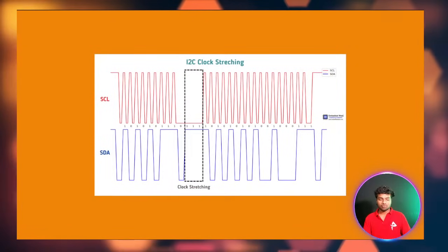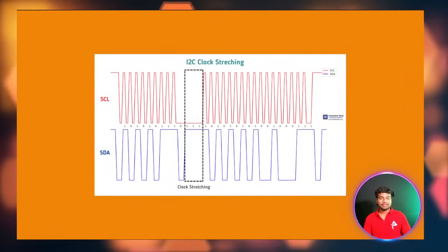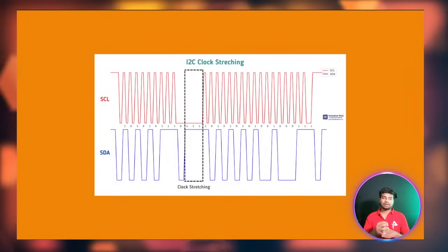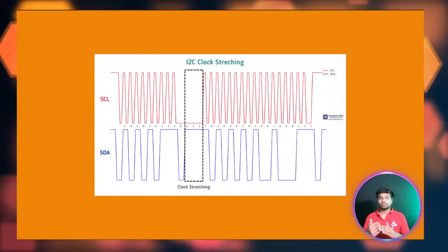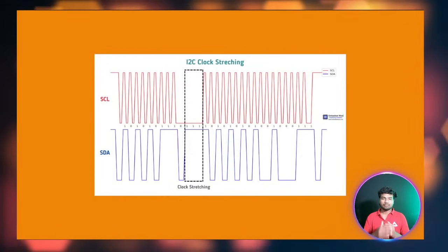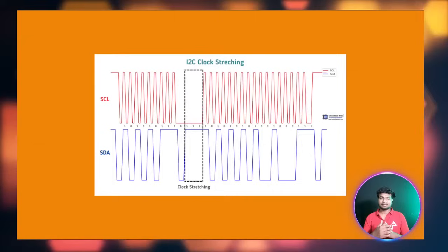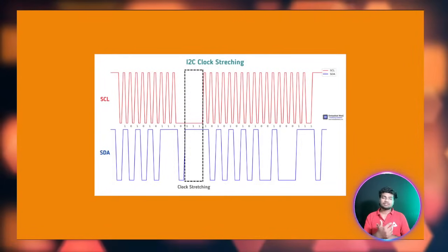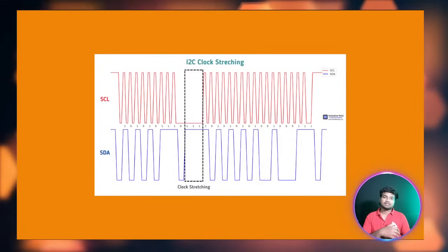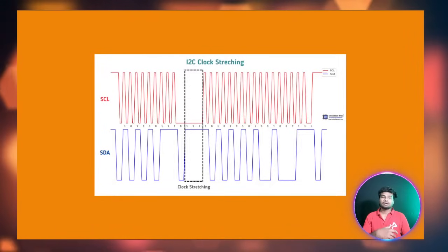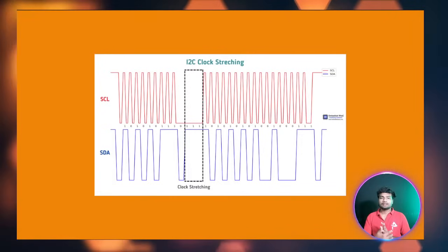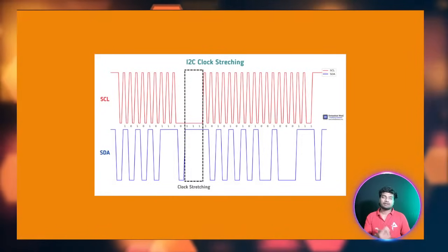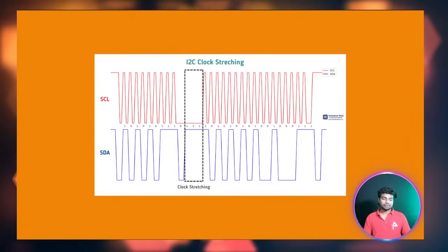If you guys have any doubt, you can ask now. The main things are clock stretching, arbitration, and frame format. So this is enough for I2C. For the coding part, if you are really interested, you can watch the code and understand easily. The main important things to keep in mind are clock stretching, arbitration, start condition, stop condition, frame format, and the acknowledgement process. Data is 8 bits, address is 7 or 10 bits, plus one read/write bit. So this is the main thing of I2C.